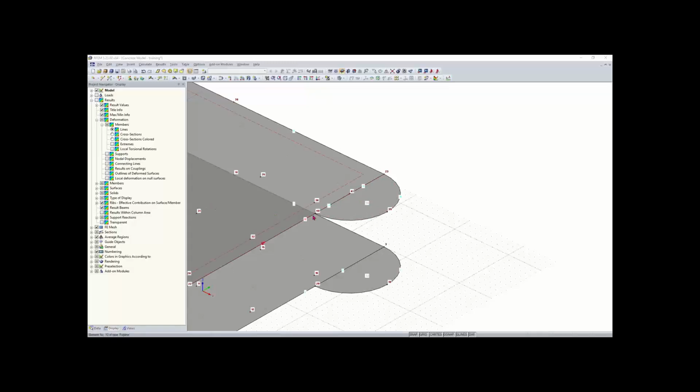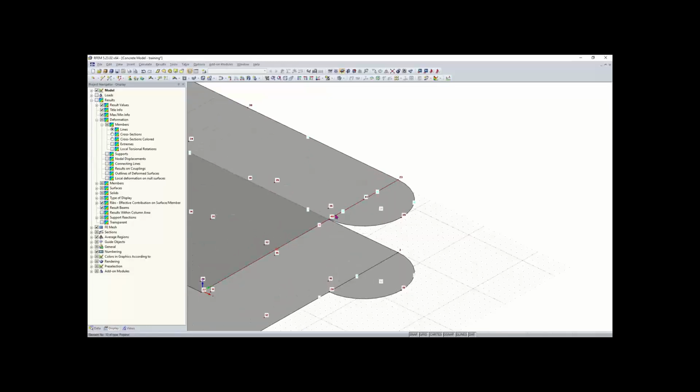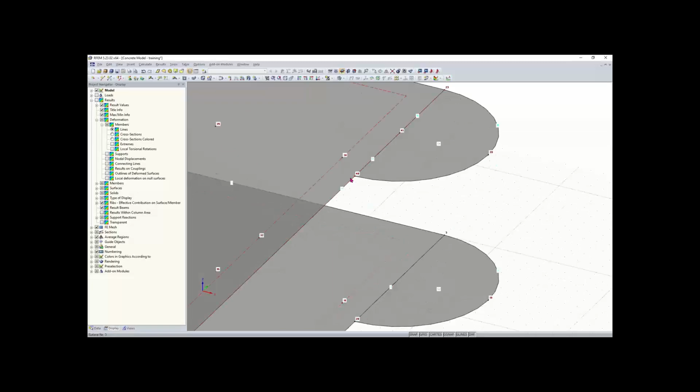And so now what I want to do is connect this line to this line at node 40 here. You can see that this line is one whole line. So if I go up here to this tool called connect line/members, I'll click on that and highlight my node there. And you can see that what that did was split that line at that node and connect them, creating two different lines and an intersection.